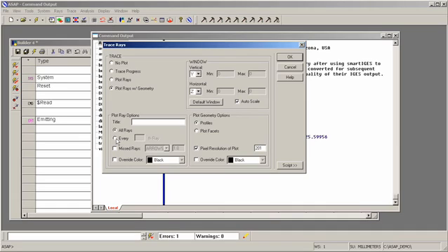And at this point, since we have a large number of rays, we do not want to display all of the rays during the ray trace. Okay, that will slow the simulation down a little depending on the graphics driver. So I'm going to use a different setting here. I'm going to tell the program to display only 1 out of every 1,000 rays.